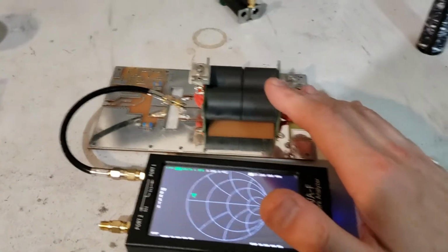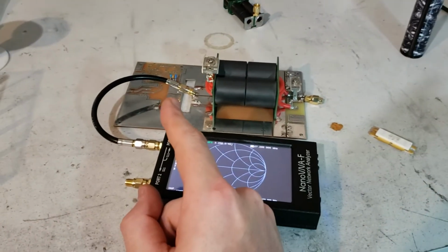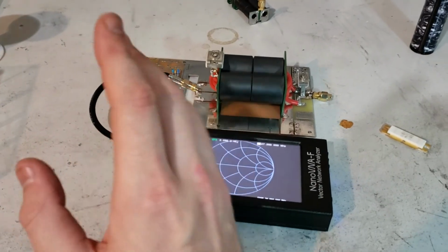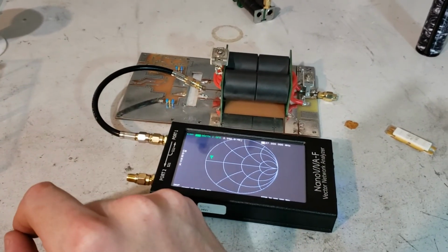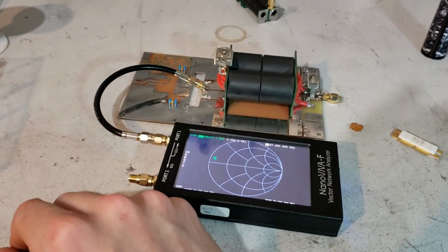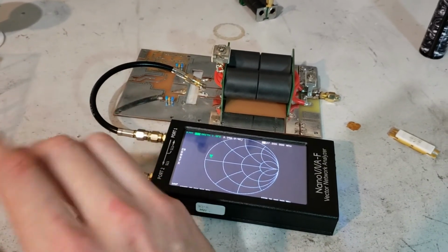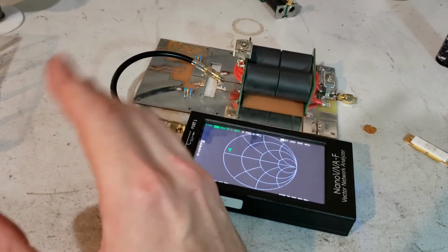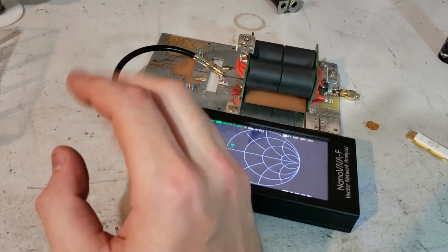For testing, when you're tuning the input transformer, you want to pay attention to your reflected power and tune your capacitors to have the minimum reflected power. So that shows you that you have a good match. That's a real easy way to tell whether your input match is good or not. Put a reflect meter in line, a real sensitive one, like a 5-watt slug or something.